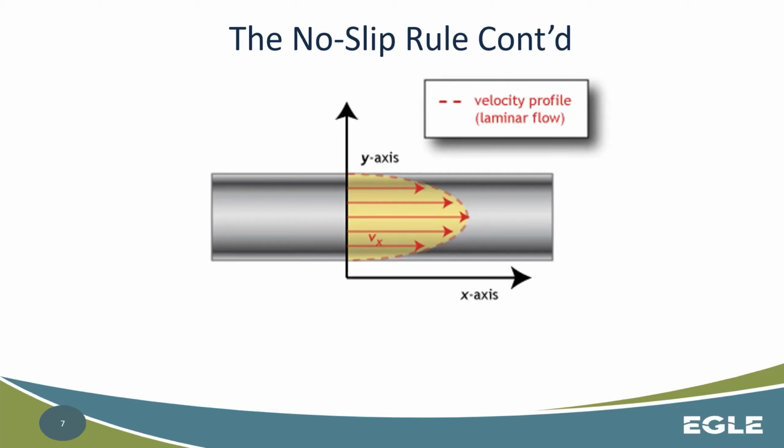When it is flowing in a laminar way, as in the picture, the water in contact with the surface of the pipe at the edges sticks to that wall, and water closer to the center that has minimal contact with that wall moves with more ease because of that. The reason is that the interaction between the sidewall and the center flow is limited. The edge of the pipe has a higher frictional interaction. So the water flowing down the middle of the pipe has the least resistance to its motion, therefore making it easier to flow down the middle.